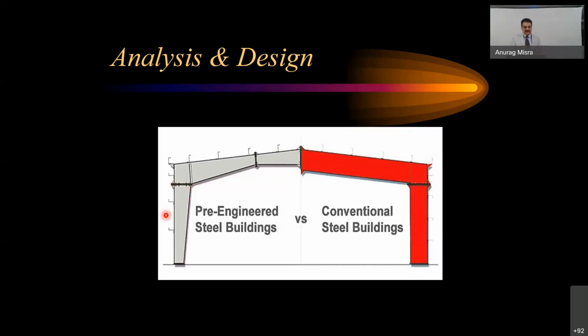These things are possible: the cutting of the plate is done in a way, and then you cut the flanges separately. It goes to the machine, the welding is done, and the built-up section is ready. Now, after doing the connection, you can see that you could actually reduce the thickness here in the beam as well as in the column.